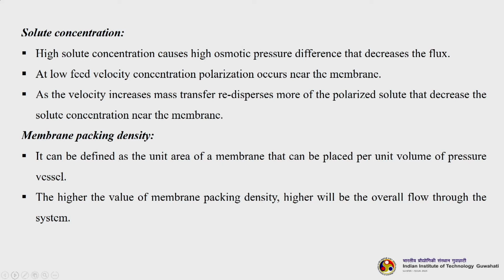The next parameter is membrane packing density. This is one of the most important parameters. You can define membrane packing density as the unit area of a membrane that can be placed per unit volume of pressure vessel. The higher the value of membrane packing density, the higher will be the overall flow through the system.